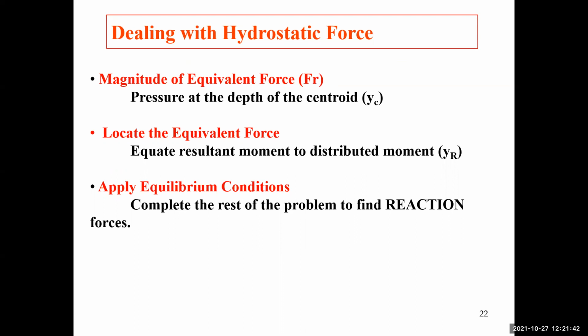We also needed to apply the equations of static equilibrium: the summation of moments about a point is zero, the summation of forces in some x direction is zero, and the summation of forces in the y direction is zero. That gives us three equations and three possible unknowns to determine, to ensure that the problem is indeed at static equilibrium.